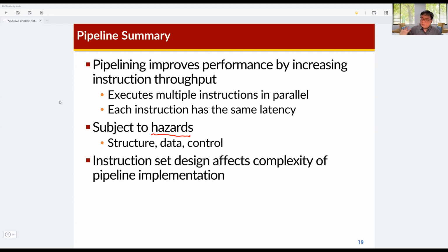The result of a branch is resolved in the ALU, that is the execution stage of the pipeline. So this resolution of the branch result is done at a late stage of the pipeline architecture. If the branch result is true, then the target of the branch is updated to the PC lately.